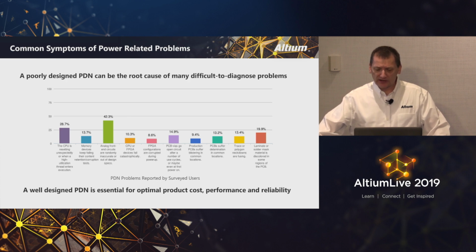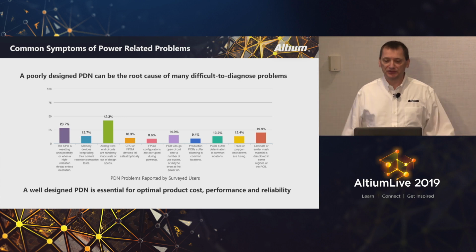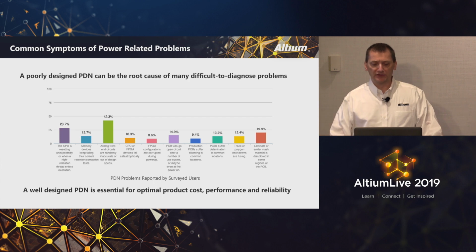I've worked with customers who have found problems in the field in the past, and then they asked us, could we look at those designs and see if we could spot them? In most cases, we're able to find things such as severe voltage drops. So a device that's not getting enough voltage to properly operate, the board will power up and start to run, but then at some point you hit an issue and it can be difficult to diagnose. So that's generally how power problems are discovered.